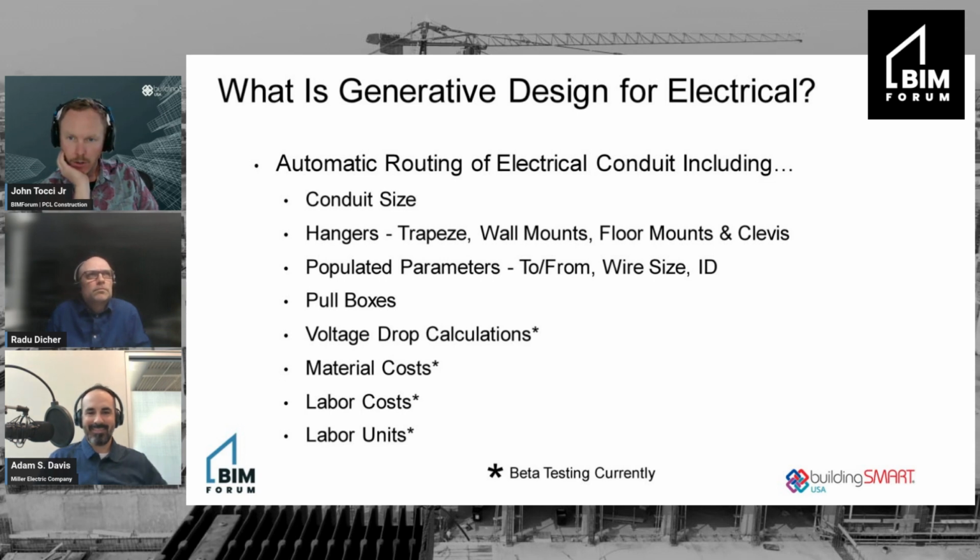The conduit size is governed by NEC. You can only fill a certain percentage of that conduit. But the size of the conductors inside that conduit are many times driven by both the amperage and the voltage that's being passed through the conductors.